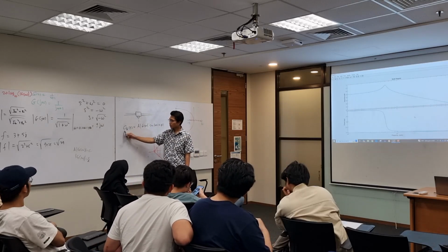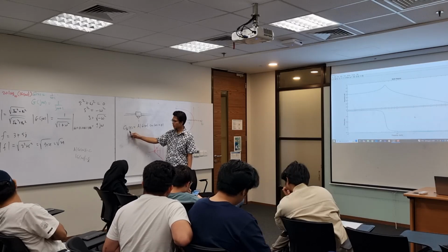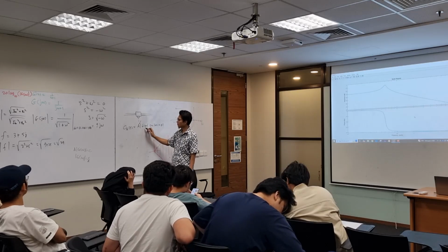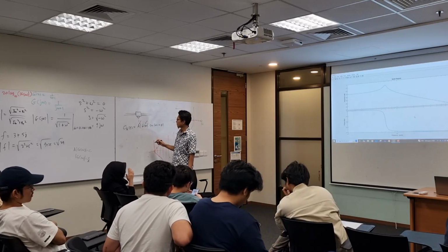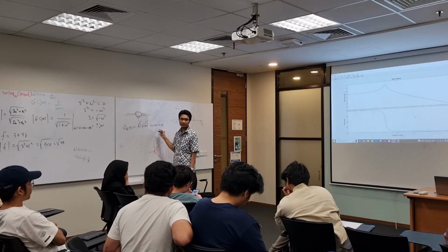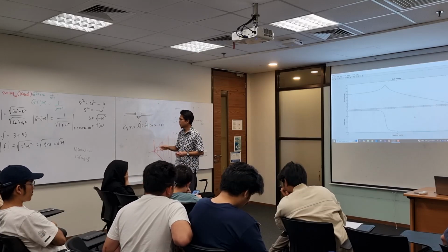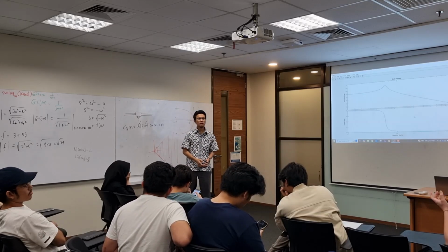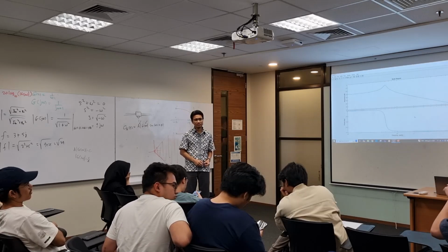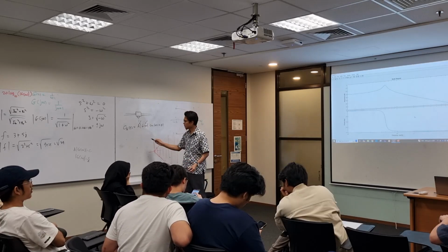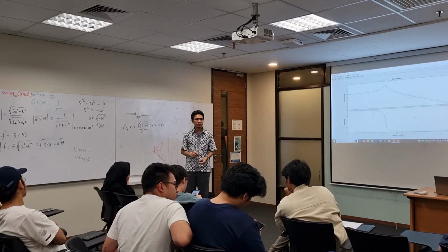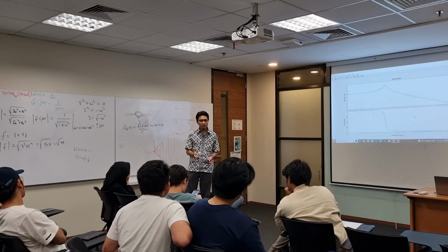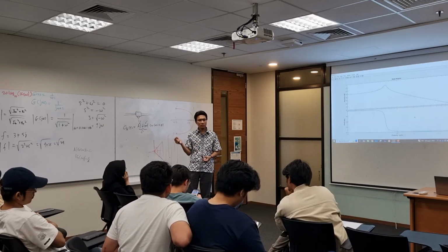So we will know our steady state response by having this input multiplied by the ratio and then multiplied by the sinusoid function itself. So this is the relationship. And then your question? So that's the C. Yeah, this is the C. Correct. What does it tell us? It tells you the response of a system after you give it a sinusoid input.